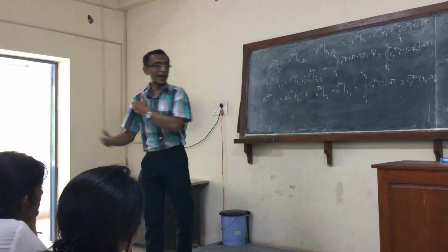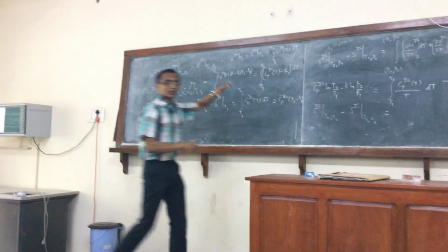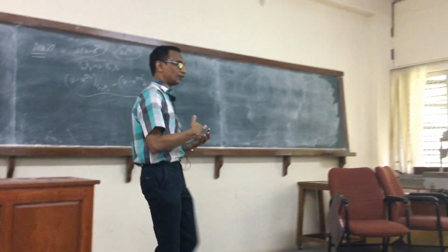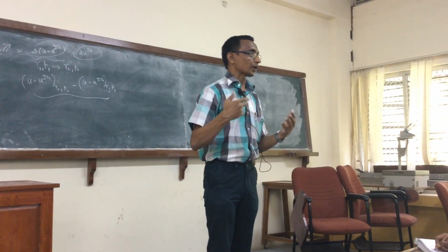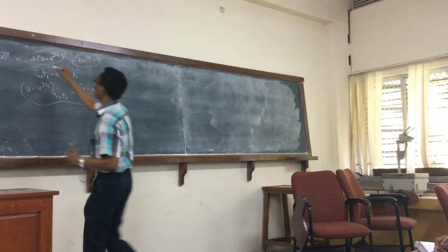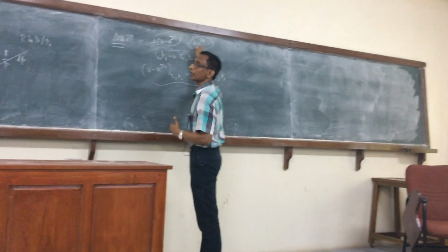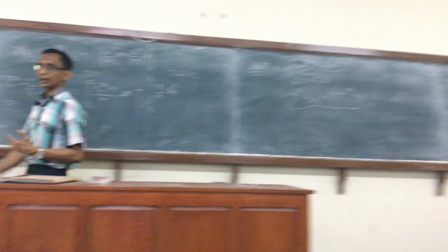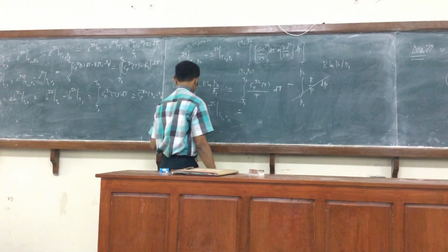So clearly in that case, I would go to the departure function, which expresses the departure in terms of T and P specification, and calculate the difference. Then I will come here. Since T and P are specified, I will use this formula for the ideal gas.